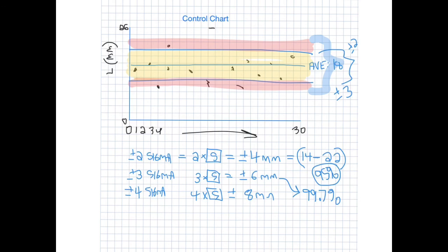We're essentially done with today's project, but just to give you an idea of what it means. So if I come up with plus or minus 3 sigma limits on my peanut example, and I get plus or minus 6 millimeters, that tells me that the entire jar of peanuts, 99.7% of the jar, will fall within that range. And I can predict that just using 30 pieces.